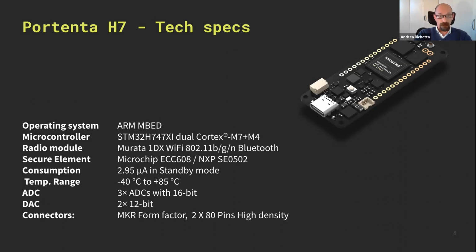And we have a really low power consumption that starts at 2.95 microamps in standby mode. And then we have temperature range, we have ADC, DAC, and then we have different kinds of connectors. One for the MKR family, and we do have also two high density connectors that provide 160 pins out of the board, where you can leverage and you can scale up with the projects.